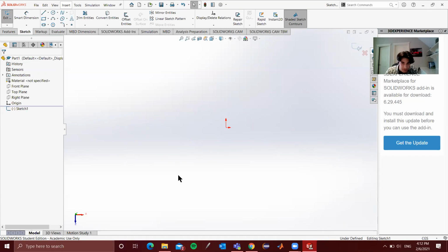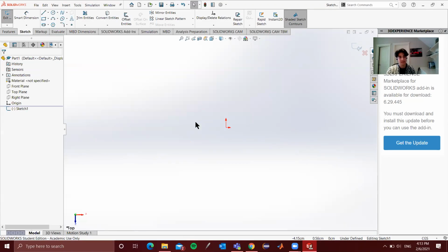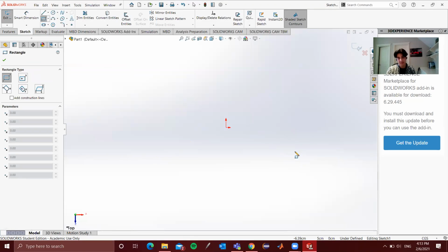But essentially, I'm going to make sure that our point of view is perpendicular to our plane. So I'm going to press this Y-axis button, which is the axis that is perpendicular to this top plane. And you have all of these different sketching tools here. All of this is in 2D, right? And upon this reference frame, what we can do is create a rectangle. So let's do that. Just a basic rectangle.